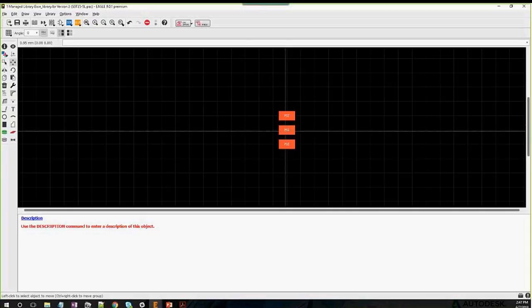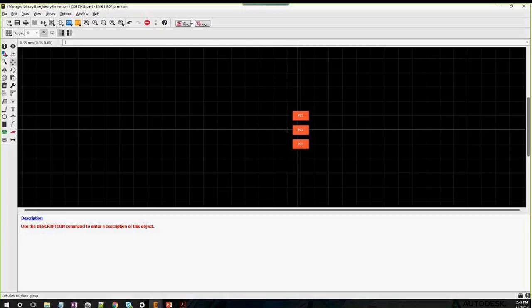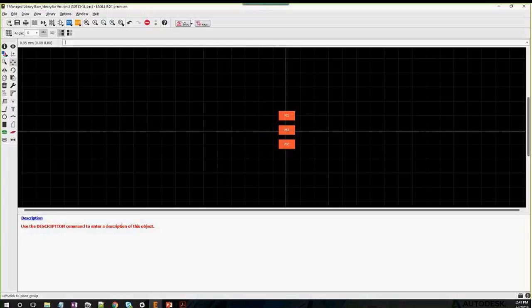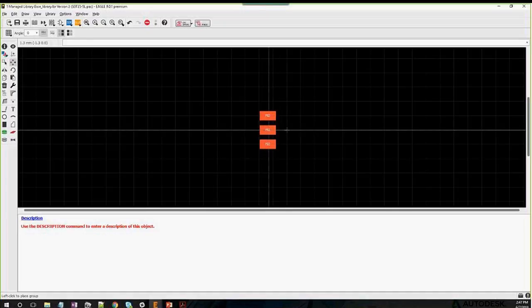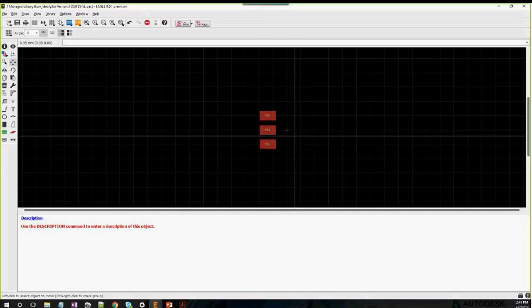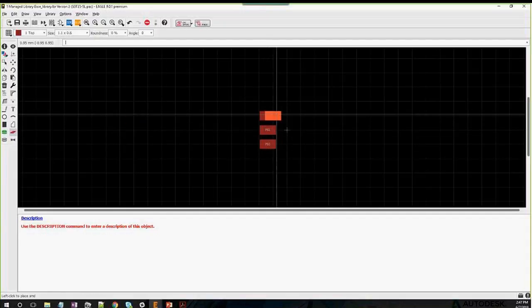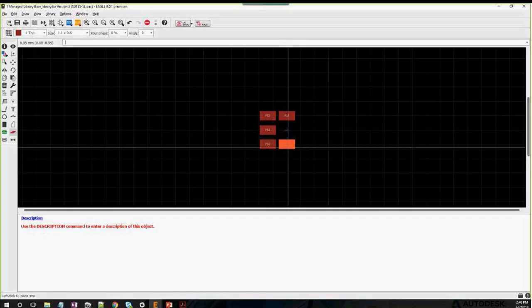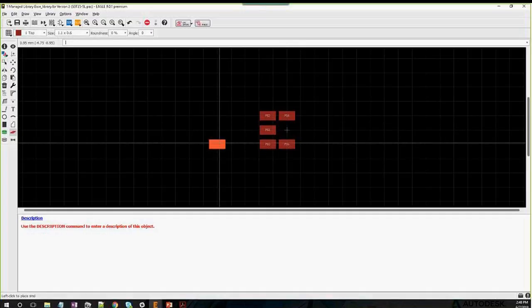You can use the move command itself, control right click moves the group. Okay, and right now it's moving in units of the default grid. If I hold Alt, it'll move in units of the new grid, of the 1.3. So there we go, 1.3 there. Perfect. And now what I'll do is I'll place my remaining 2 pads. I'll put them over here.